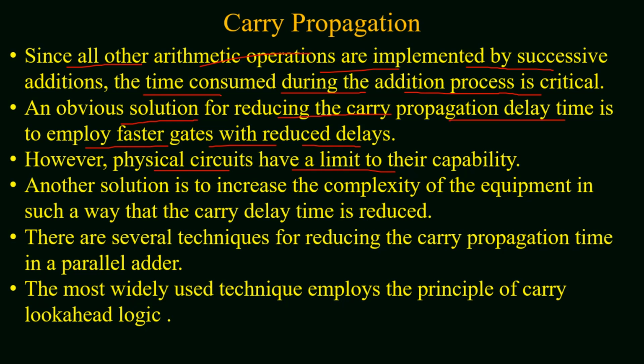Another solution is to increase the complexity of the equipment in such a way that the carry delay time is reduced. For this purpose, several techniques are available for reducing the carry propagation time in a parallel adder, and the most widely used technique employs the principle of carry look ahead logic.